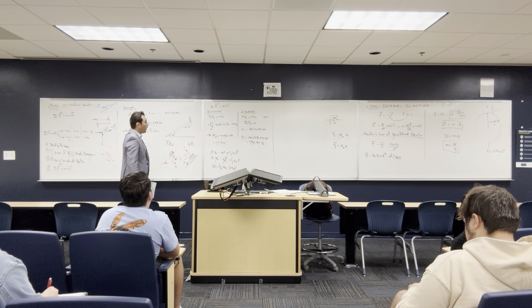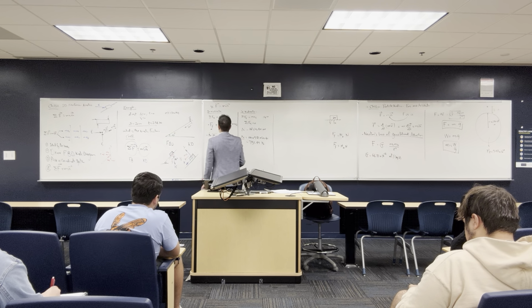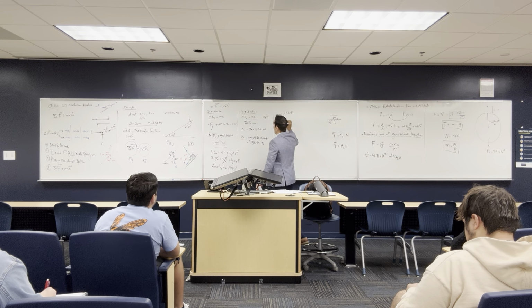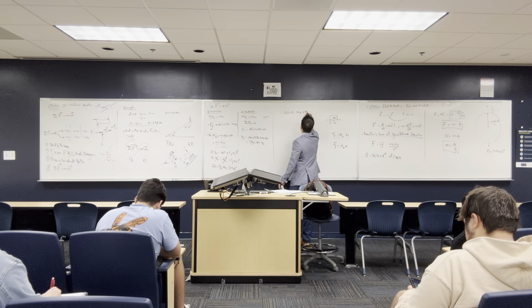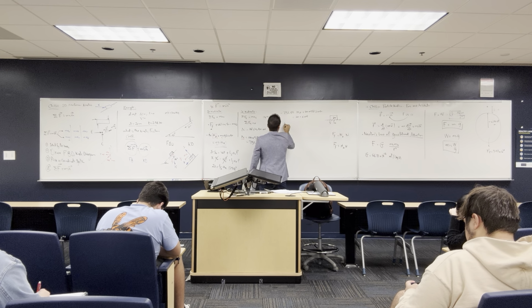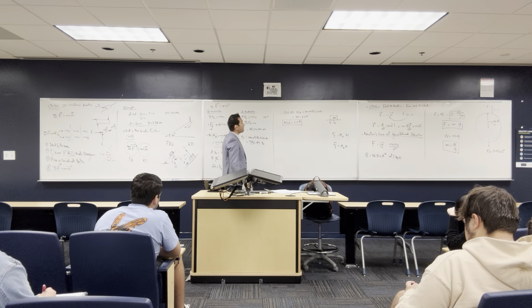Okay? All right, so let's substitute in this equation. So I have negative the normal force you just got, 751.49, multiplied by mu, the friction coefficient, and then plus mg, the mass is 100, the g is 9.81 multiplied by sine 40. All this should be equal to the mass, 100, and I just got the acceleration is 6.009. If you calculate all this, you will find that the friction coefficient is equal to 0.039, and I can write it like this. Okay?